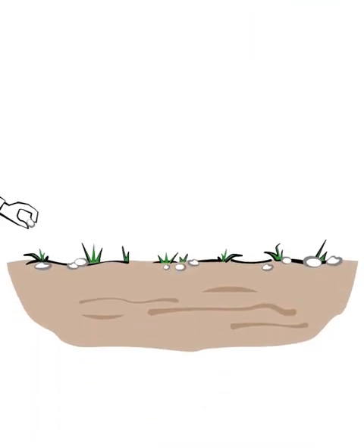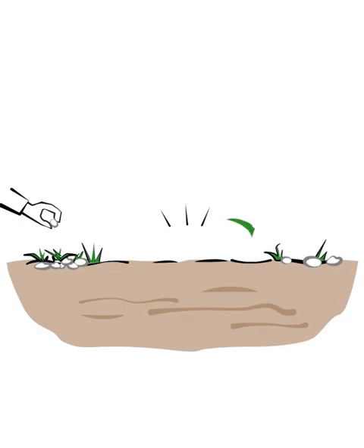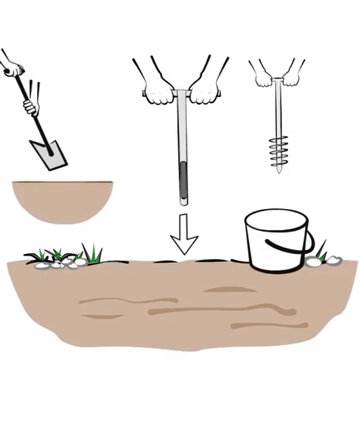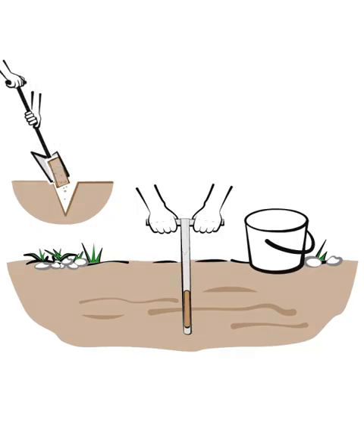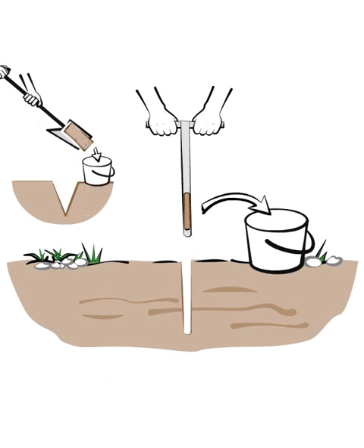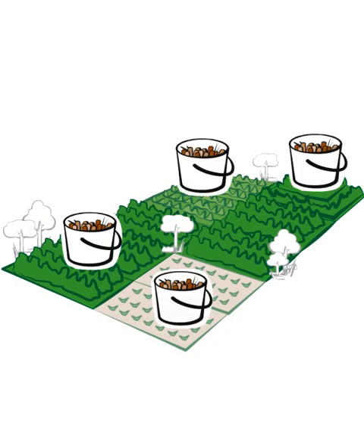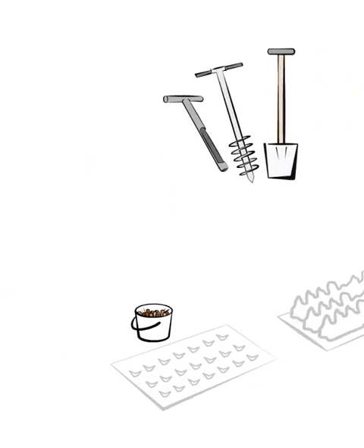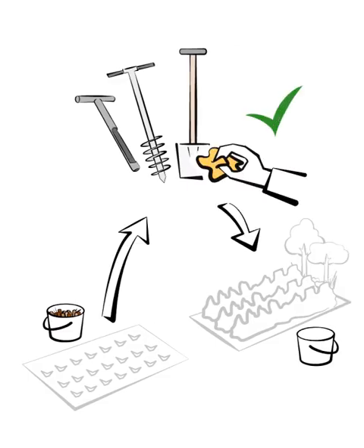Prepare each sampling point by removing leaves, weeds, stones, and other surface litter without removing soil. Then proceed with sampling. Collect 1 soil subsample at each sampling point. Use a clean spade, hoe, machete, or auger to open a small hole or V-shaped cut in the soil and remove a thin, vertical slice of soil down to a depth of 15 to 20 centimeters or 6 to 8 inches. Place all subsamples from the same block into the same clean bucket or container. Together, these subsamples represent the block. Clean the auger or spade after sampling each block.